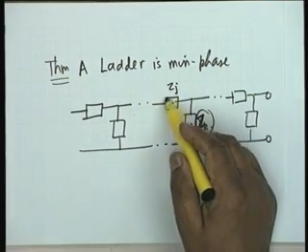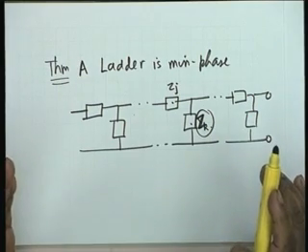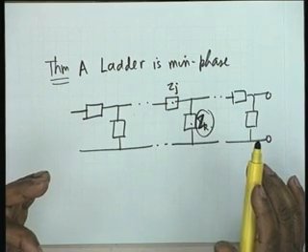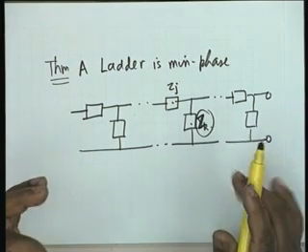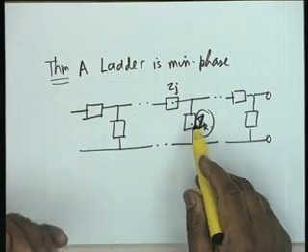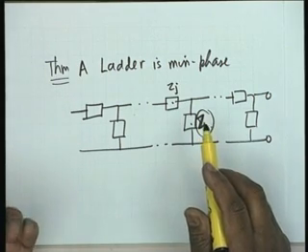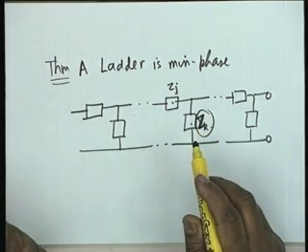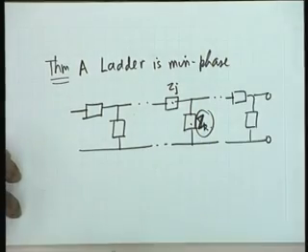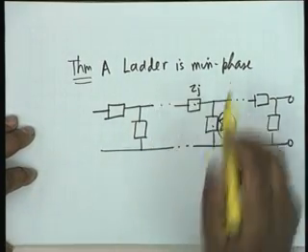It is either a series impedance pole, now we state it in formal language. The transmission zeros of a ladder are constituted by two kinds of frequencies: those at which the series impedances have a pole, or shunt impedances have a zero. And since any driving point impedance has poles and zeros in the left half plane, the transmission zeros of a ladder must be in the left half plane. In other words, a ladder must be minimum phase.